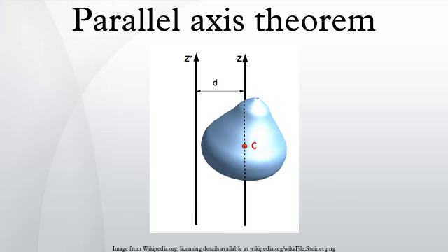Moment of inertia matrix. The inertia matrix of a rigid system of particles depends on the choice of the reference point. There is a useful relationship between the inertia matrix relative to the center of mass R and the inertia matrix relative to another point S. This relationship is called the parallel axis theorem. Consider the inertia matrix obtained for a rigid system of particles measured relative to a reference point S, given by the following, where r_i defines the position of particle P_i, i = 1, ..., n. Recall that [r_i - S] is the skew-symmetric matrix that performs the cross product.